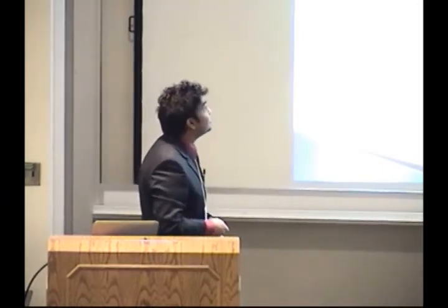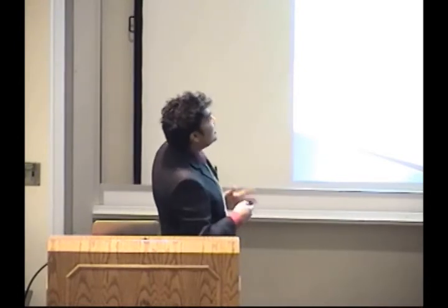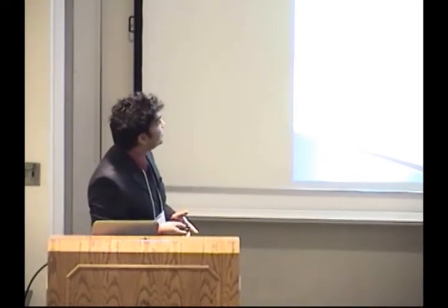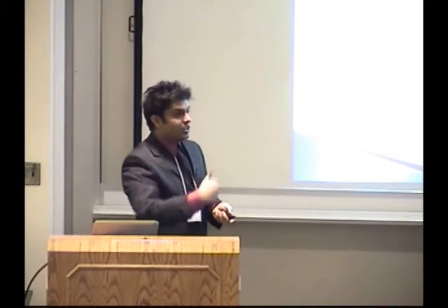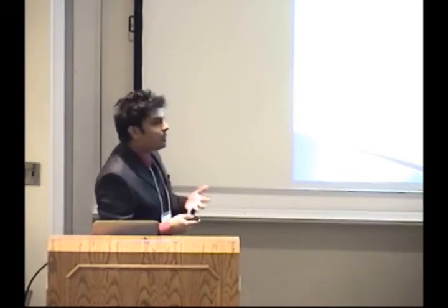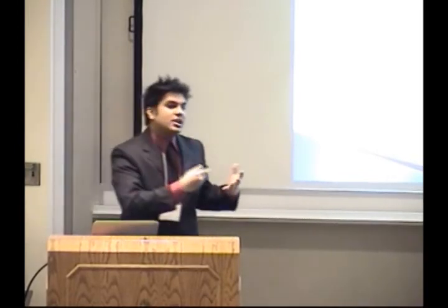So what's next? We want to try and optimize our system, so find out what the limits of performance are. Maybe we can apply an adaptive threshold to deal with these distance and brightness issues. For instance, in that same situation I mentioned before, the more distant LEDs would have a lower threshold, so they would actually get classified more than the closer ones, which are brighter. And we want to develop a probabilistic model saying, am I 90% or 95% confident that this will hit the threshold within a certain time, and then we can classify it that way.